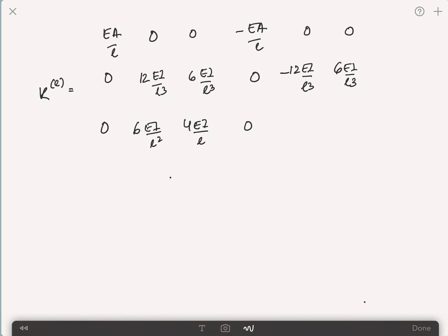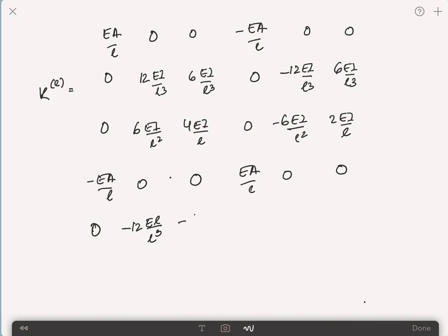Of course, you see that I have brought in the coefficients inside because they are not common for both the matrices. So it's important for us to also make sure that we have the right stiffnesses in the right locations. So these are for the 1 degree of freedom in the one direction, and then you have the rest for transverse and bending. So it's basically just copying the terms from each of the element matrices for truss and beam, so we can assemble it together to make a frame element.